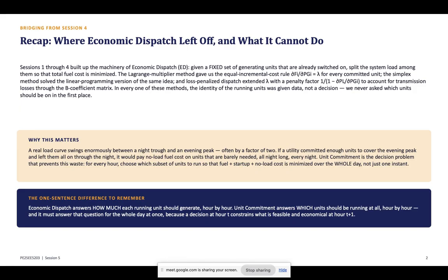A useful operational analogy is to separate permissions from allocation. Unit commitment grants a generator permission to participate in the next operating period by bringing it online. Economic dispatch then allocates the actual megawatt share among the permitted generators. This explains why an economic dispatch result cannot be computed meaningfully for a unit that is not committed yet. Its operating interval does not exist in the current feasible set. As simple as that. So the opening material should be read as the frame for the complete session. The later numerical work will be easy for you.